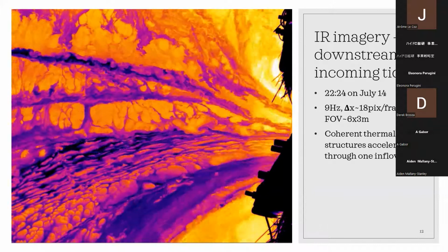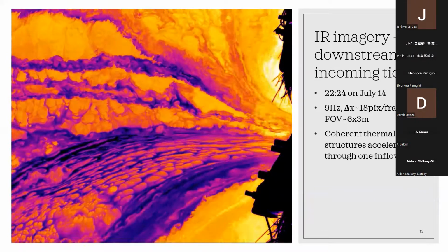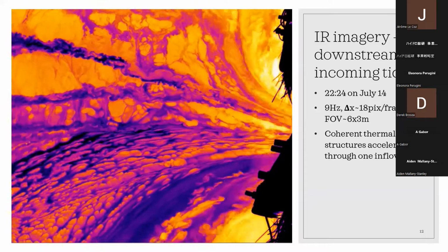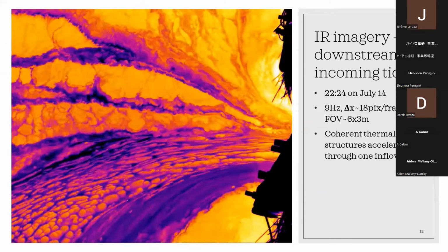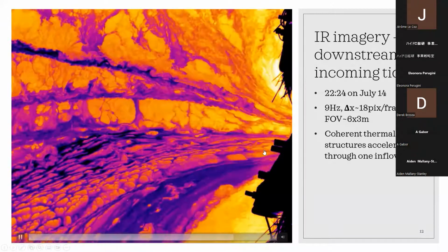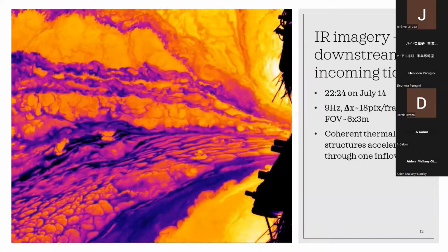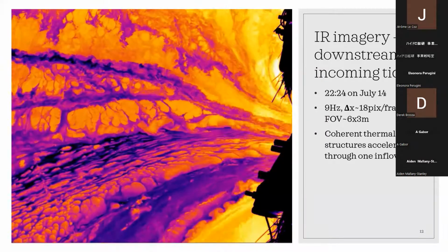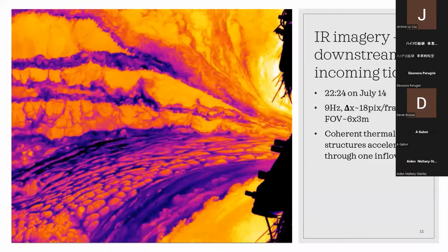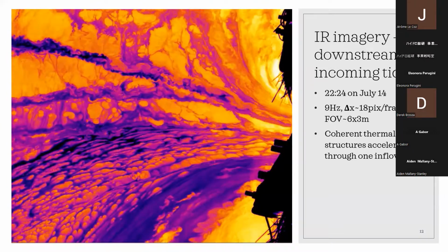Yeah, that's something that our group does have some experience in. I can't speak to the exact methods we'll use, but another nice thing about this system is all this water is basically going through a culvert at the end of the day. So we'll look at the bathymetry and see how far out we can place that line. But as a backup plan, we can just run it through the dimension of the culvert itself, right at the entry point. Obviously you have your no slip boundary conditions at the bed, but in general, like Seth's talk showed, you do get very good agreement between an ADCP method and the IRQIV in many settings. So it's definitely something we'll have to look at, and that's also why we have the acoustic instruments in the channel, so we'll be comparing with those as well.